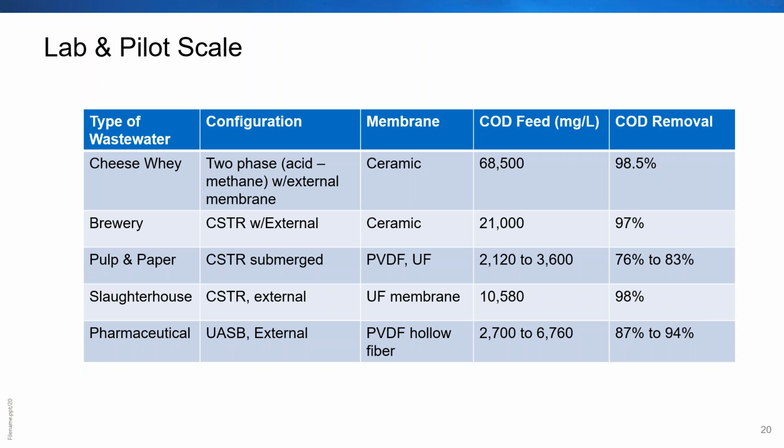On the brewery side, they did a reactor with external membranes. Similar, they used ceramic membranes. The feed wasn't quite as concentrated as the whey facility, but likewise, they're getting good COD removal. This was also pretty small, about under 5 liter reactor tank. So again, very small lab scale.